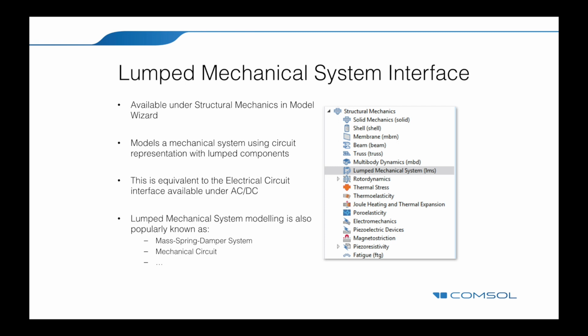In this slide you can see a branch of the structural mechanics and the multibody dynamics interface. We will use the lumped mechanical system interface, which is similar to an electrical circuit interface. You may be familiar with the SPICE netlist. In the lumped mechanical system you can solve for scalar displacements and forces, so we will solve ordinary differential equations without a space dimension.